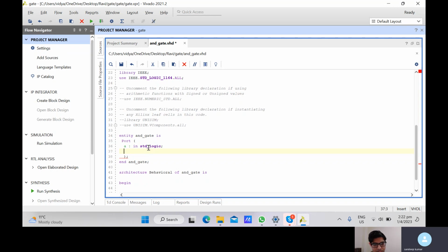We define it just as Z. So basically 9 types of logic, right? 0, 1. High impedance means Z. It's called Z. Z means high impedance. And then U is there: U means unassigned. X means don't care. These are literals, which say what is 0, what is 1, and then Z, what is U, what is X. So these literals are possible values of A.